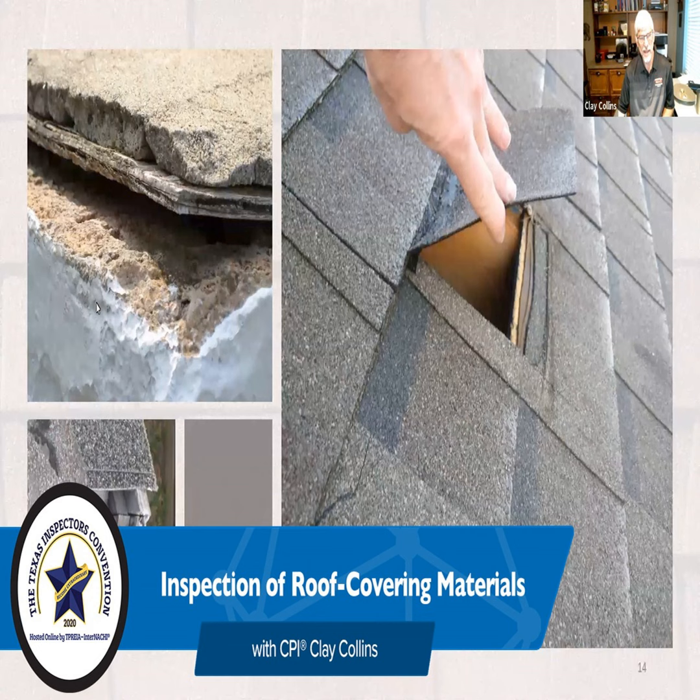And especially down here in the lower right, what you see is instead of overlapping, they just took a utility knife and cut right down. So if there's a problem, I assume that they're going to, and in fact, I know for a fact that they did, when they laid the opposing underlayment, they cut it again.